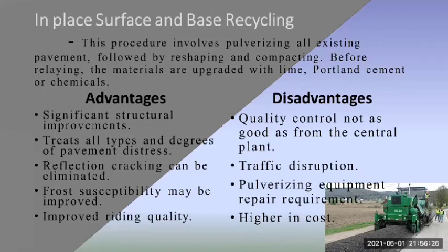Improved riding quality. The disadvantages of in-place surface and base recycling are quality control not as good as from the central plant, traffic disruption, pulverizing equipment, repair requirement, and higher cost.